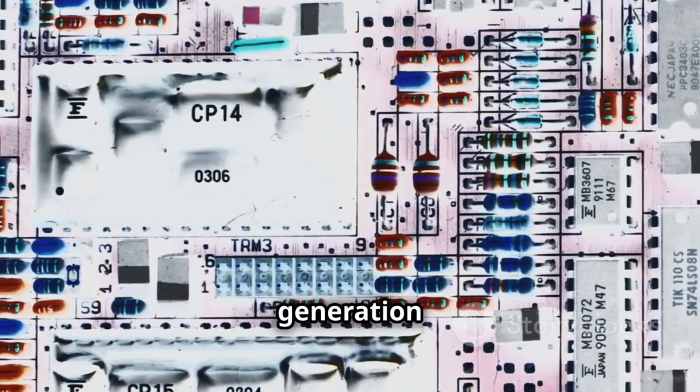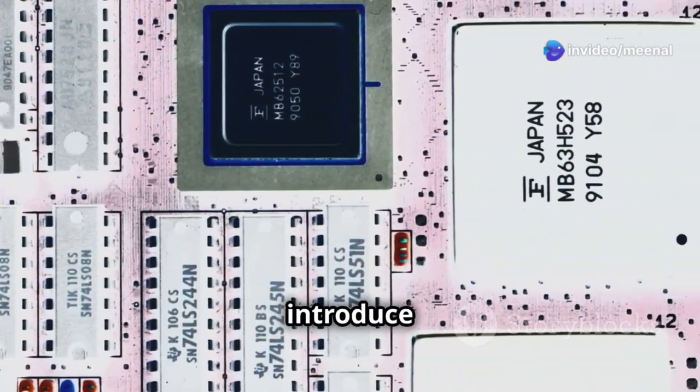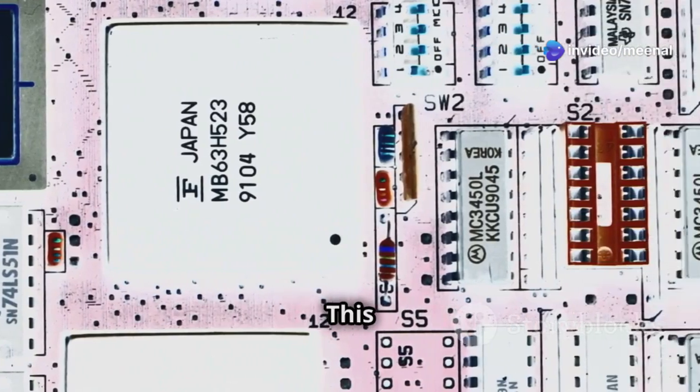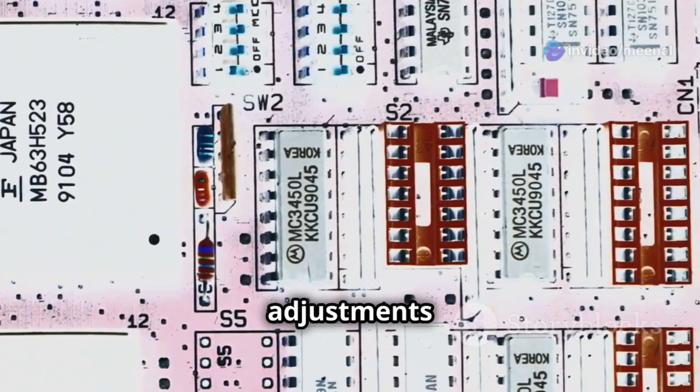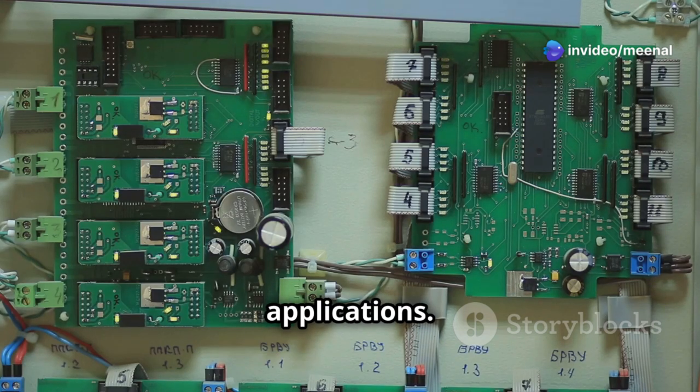Time delay generation. SISO, serial in serial out shift registers, can introduce time delays in digital circuits. This is particularly useful in timing adjustments and synchronization tasks. The amount of delay depends on the number of flip-flops and the clock frequency. By adjusting these parameters, precise control over timing can be achieved, which is critical in many digital applications.